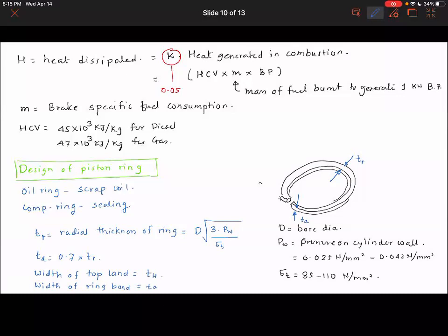What you want to do is make sure that these dimensions actually make sense when you're creating the CAD geometry. Some of these dimensions are based on geometric considerations rather than strength considerations. So if you think the geometrical constraints are not satisfied, then you are welcome to change these dimensions within the prescribed guidelines.